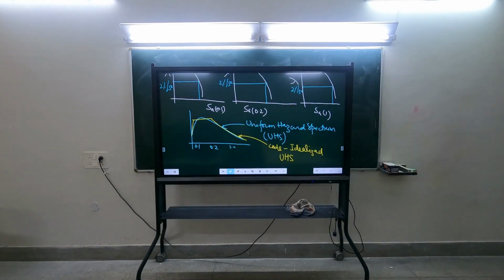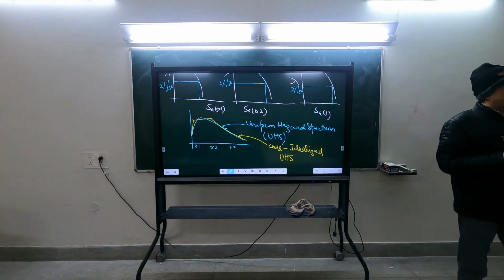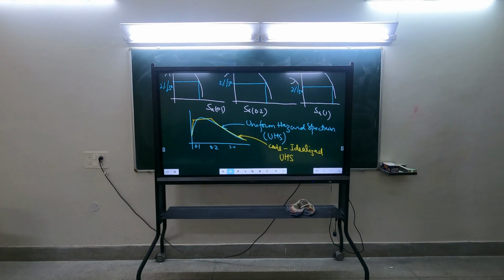In some cases, if the hazard is dominated by one single source, you can get it from one earthquake, but in many cases you will get it from different earthquakes. So it is not the shape of the response spectrum of a real earthquake. This is a shape obtained from an envelope of different earthquakes.